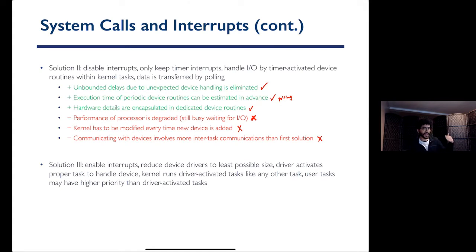So when an interrupt happens, in general purpose operating systems, you're going to handle the interrupt. Whatever interrupt has happened, you go and handle it. Now we're going to change that. We're going to let interrupts happen. When an interrupt happens, a general interrupt handling routine is invoked. And this interrupt handler is going to create new tasks to eventually handle the interrupt.